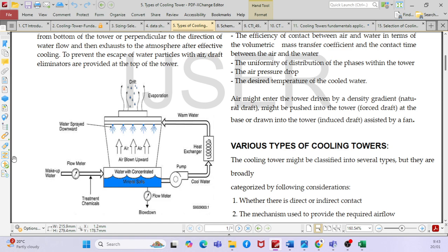So when the 950 passes through the chiller condenser, what will happen? There will be a reduction in flow, and the reduced flow will not cool the condenser properly, so it will affect the chiller capacity, right? Now whatever the losses, you have to have makeup water. So what are the losses? Basically, you have drift losses, evaporation losses, and blowdown losses.